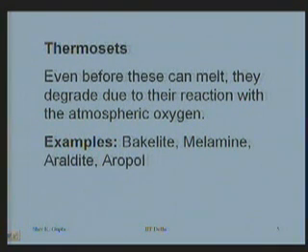As a result, sometimes the contact can become loose and there could be constant sparking. If that is happening, you sometimes smell something, and it is the burning of bakelite. So with heat, instead of softening, it starts burning. That is degrading: it combines with atmospheric oxygen and burns off. That is the kind of thing that happens in thermosets.